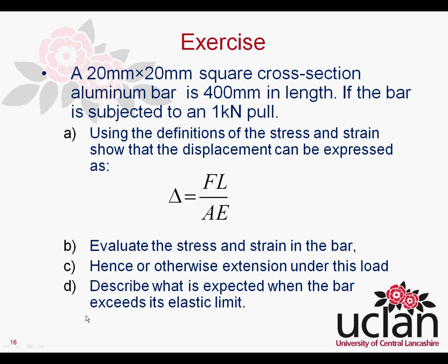This time we have a square bar, so nice and easily, a 20 by 20 square bar and a length of 400 millimeters. If the bar is subjected to 1000 newtons, we need to use some definitions of stress and strain to show that the displacement can be expressed as this. We evaluate the stress and strain in the bar, hence or otherwise, that means use what you've developed before in the question, or by your own methods, extension under the load, and describe what you'd expect when the bar exceeds its elastic limit.